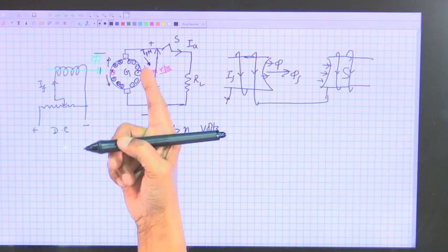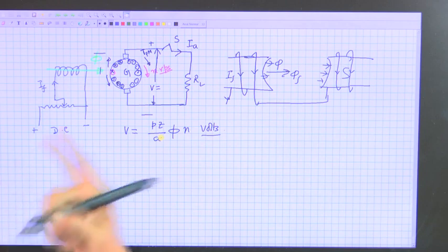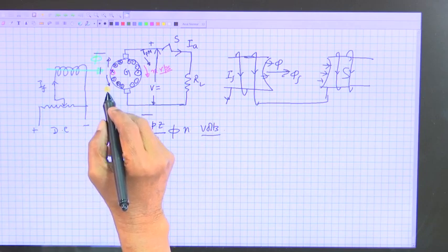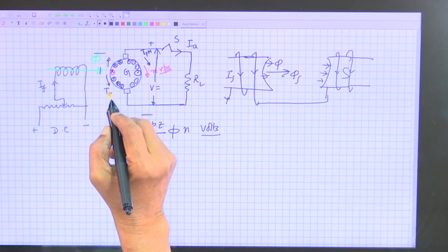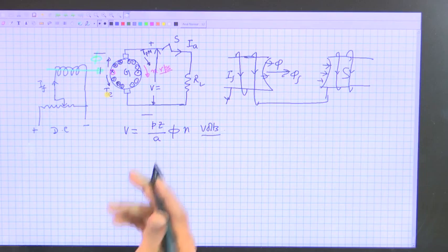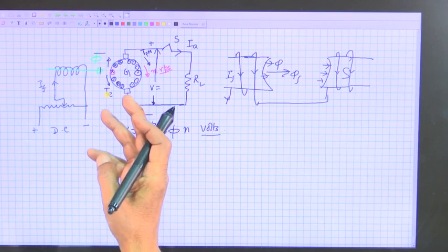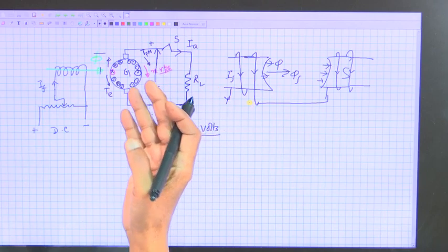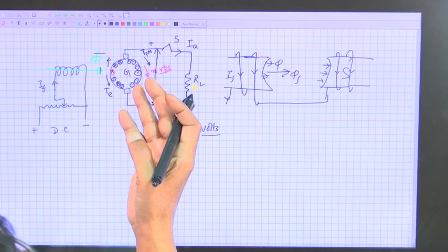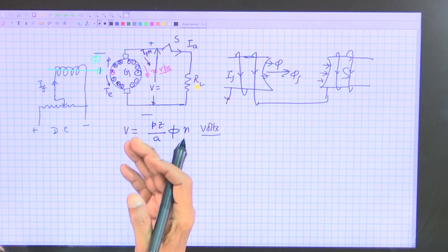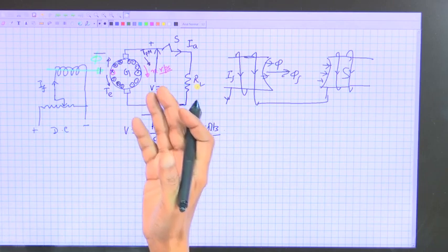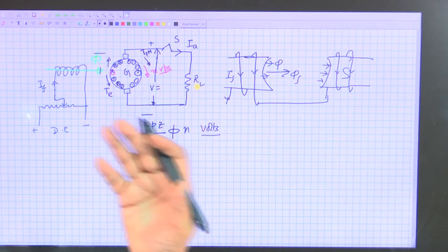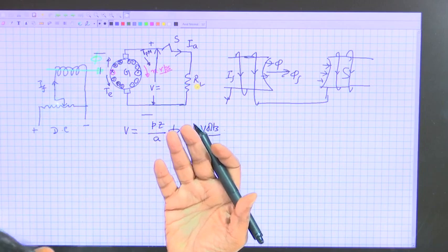Prime mover thing is a mechanical thing, who is providing you the torque, electromagnetic torque. And if you find the generator is supplying power running at a constant RPM or RPS, you will conclude the prime mover torque and electromagnetic torque are same.